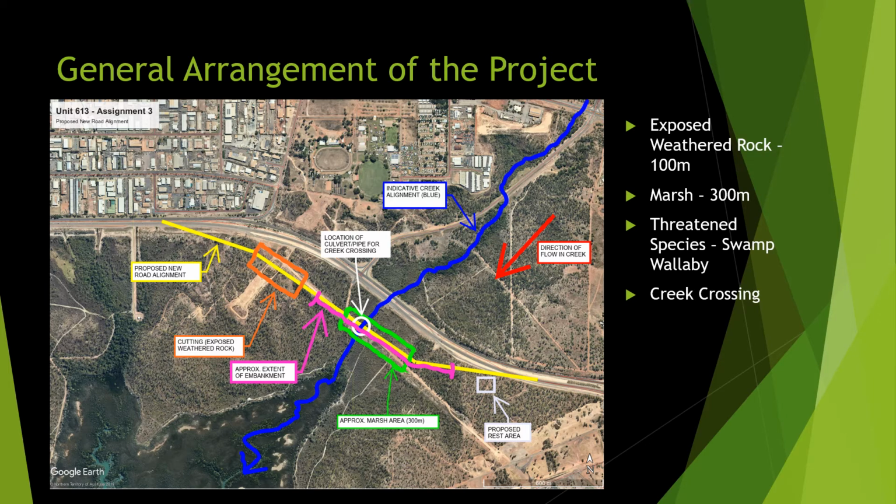So a site plan has been marked up here showing the elements that need to be considered in the construction of this project. I'll turn on the pointer again. We've got a creek which is indicated by this blue line here, an existing creek, so we have to allow for a crossing somewhere along the center of the alignment, likely being a pipe culvert crossing, a reinforced concrete pipe.